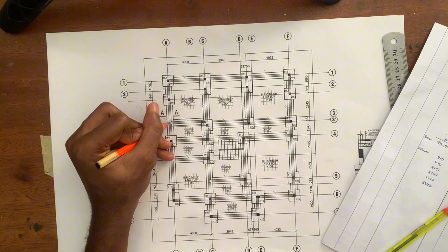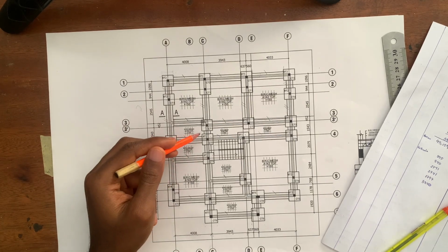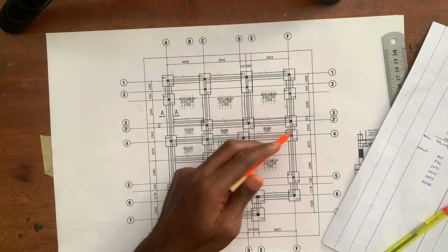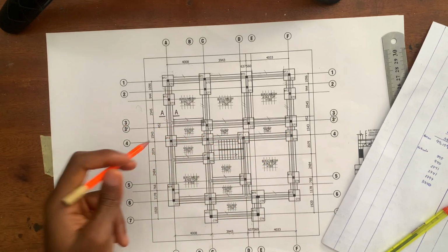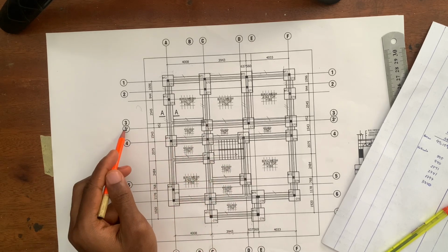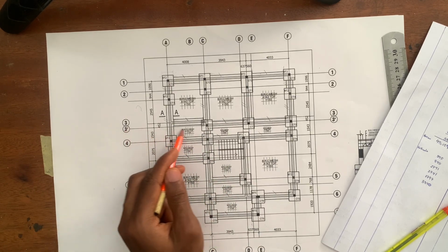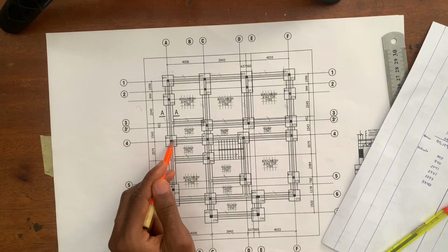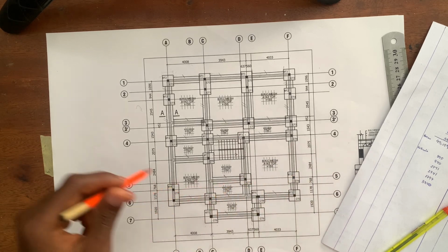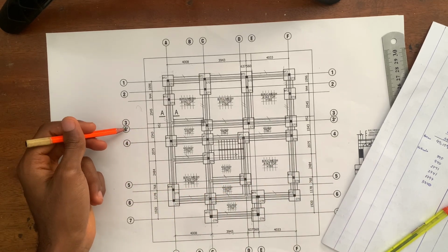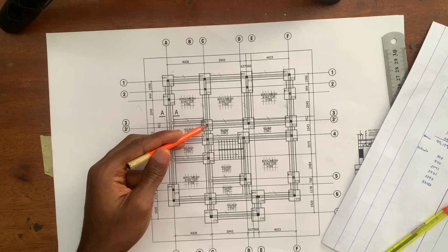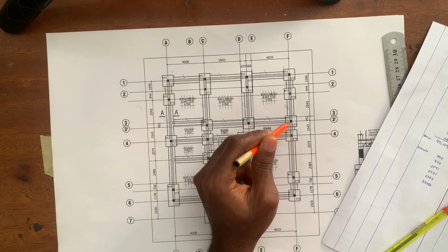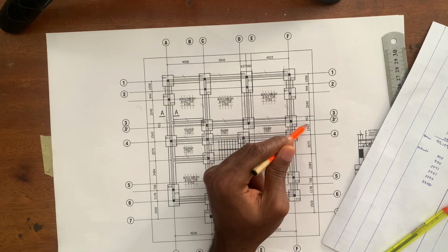So we have measures for this part. The next vertical trench we're going to be working on is this small little one here and this one. As you can see, they are similar. Why do I say so? Because if you look at call out 3 prime, it is in between here, here, and here. Similarly, call out 4 is passing through that point. So we know that the distance from this midpoint to this midpoint is 1543. Similarly, the same thing here, from this midpoint to this midpoint, 1543.